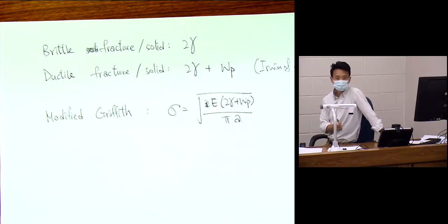The fracture strength is not a material property. By now we should know that, because it varies with samples and it varies with crack size. So it's not a material property like elastic modulus, right? You give me a material, it must have the same value. So it's incredibly difficult to use, and therefore we don't like to use it.